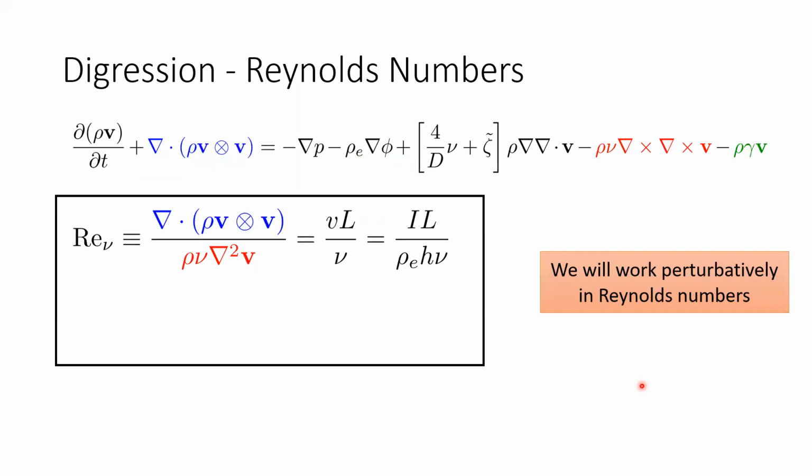There's something called the Reynolds number, which is a dimensionless quantity you generally use to characterize how strong the nonlinearities are in a fluid. It is defined precisely as the strength of the convective force to the shear viscosity. Of course, these quantities are position dependent and complicated and require you to solve, so what you do is take dimensional analysis estimates to get a handle on how strong the nonlinearities are in the system.